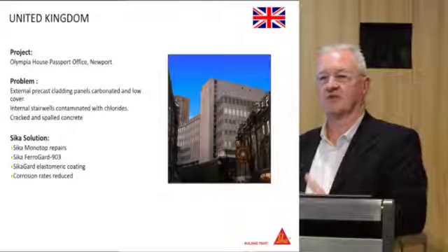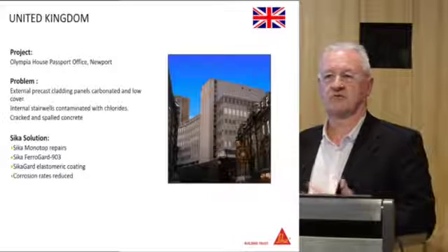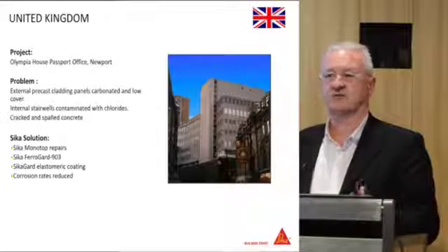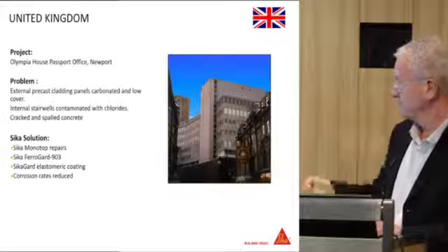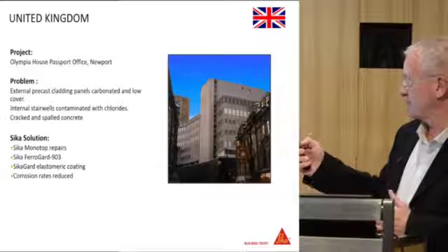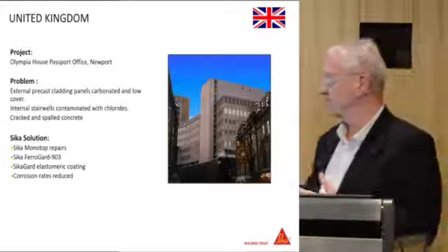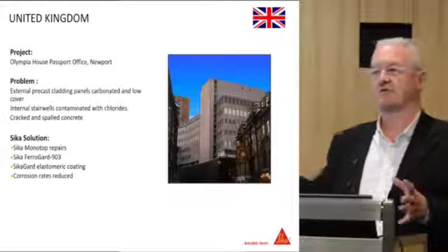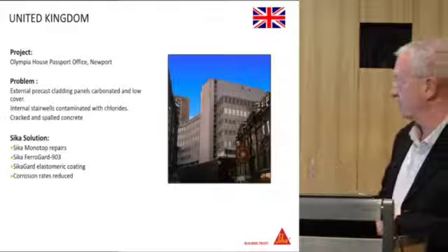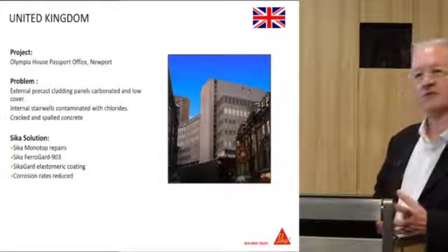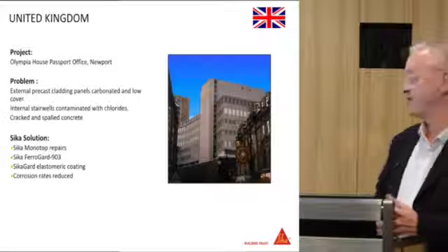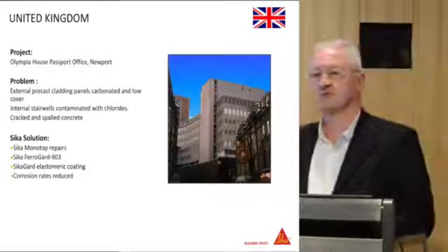The structure was actually monitored. It was a government building, so they wanted to see that whatever had been proposed was actually going to work. So there were quite a few levels and quite a few readings around the building. This is just typically one of them. And we were finding that on part of the building, we had about 158 microns a year of corrosion products